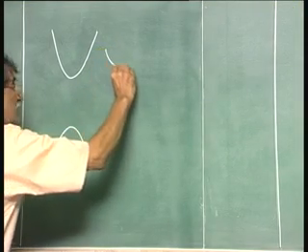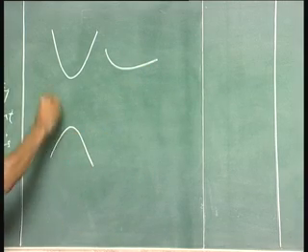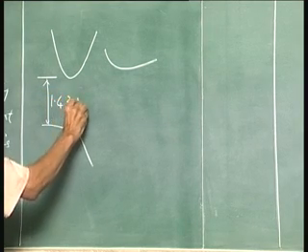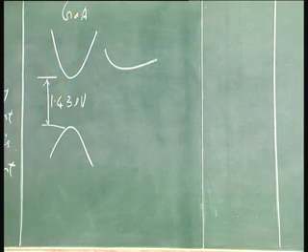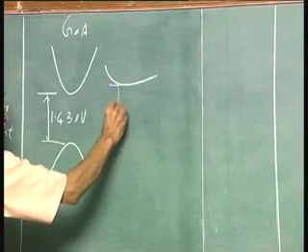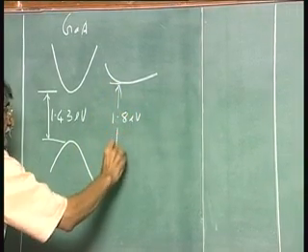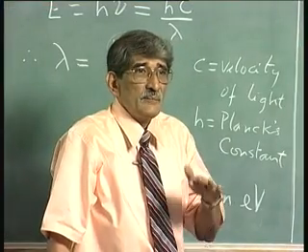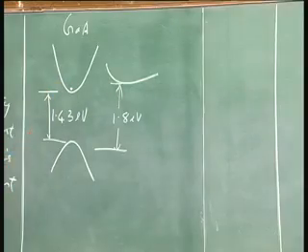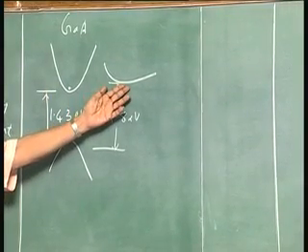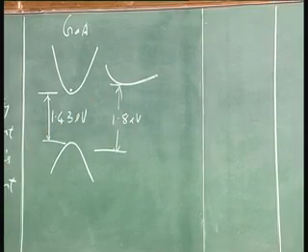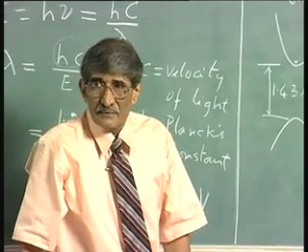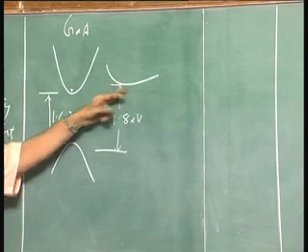okay, and that is the satellite valley, which is the gallium arsenide. So, if I have this as 1.43 electron volts, that is gallium arsenide, you will have this as 1.8 electron volts. You do not care about that, because the electrons tend to occupy the minimum energy position, that is that. It will not occupy this position unless you give enough energy by some external means like electric field, then you can scatter it from here to here, otherwise it will remain here.